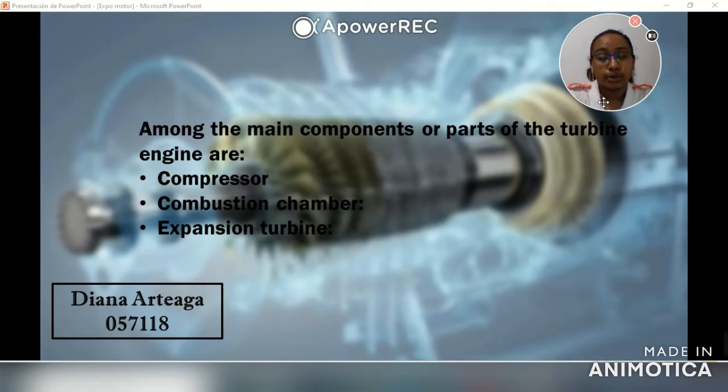It is a process that consumes a lot of energy, up to 16% of the energy produced by the turbine. To reduce the power required for the process, you can opt for a design that cools the air in intermediate stages, favoring its compression. In total, this reduces the efficiency of the turbine due to the colder entry to the combustion chambers.